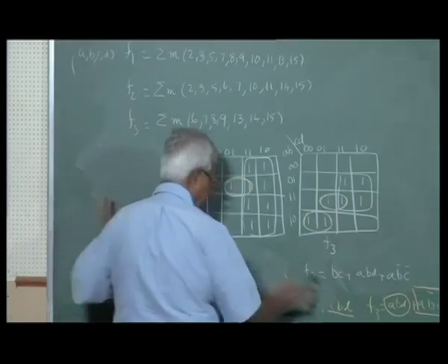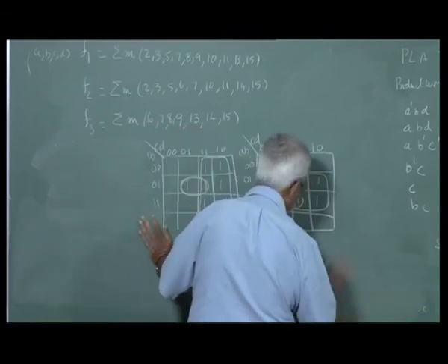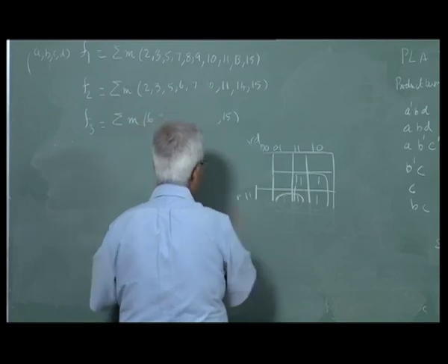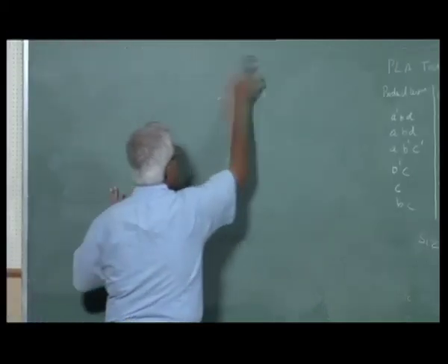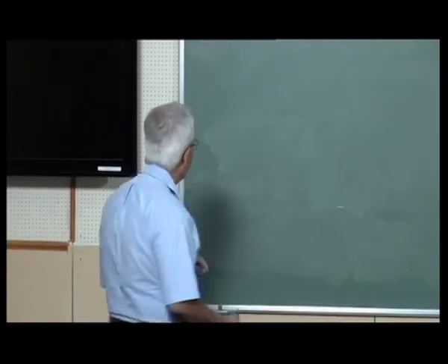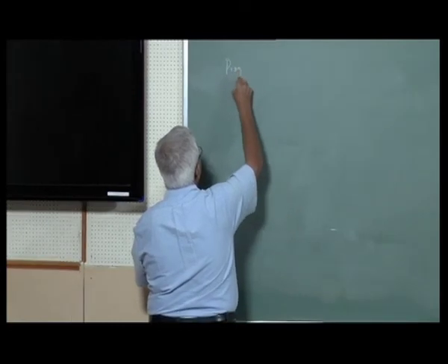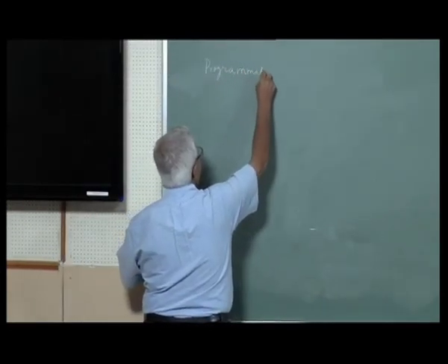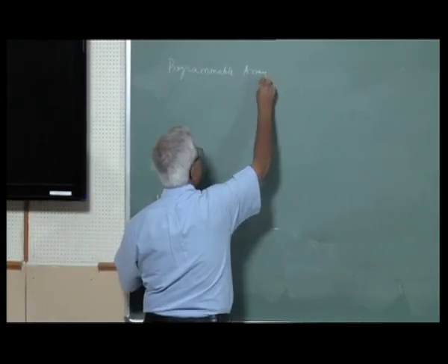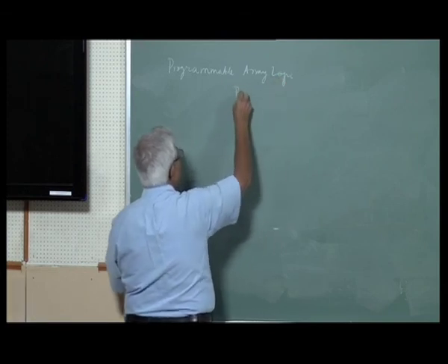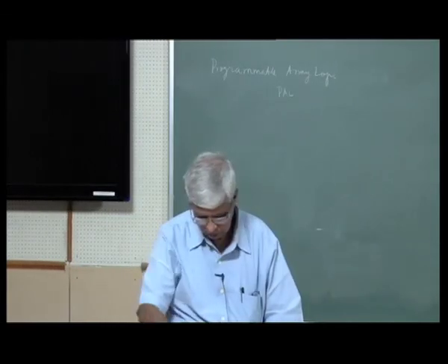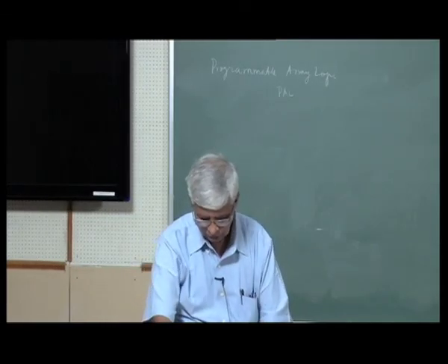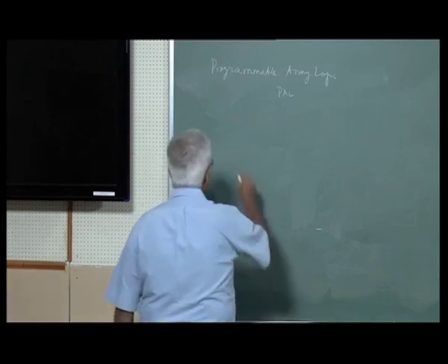This programmable logic array is good, except that we have to do all this programming and find out the common minterms, etc. The programmable array logic: one is PLA, the other is PAL, in which we will have a programmable AND array as we defined earlier.